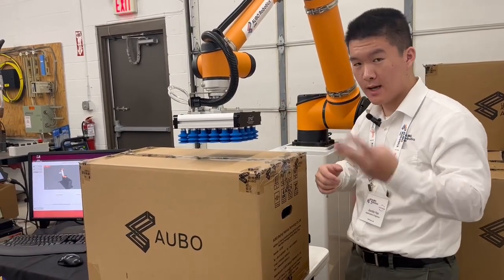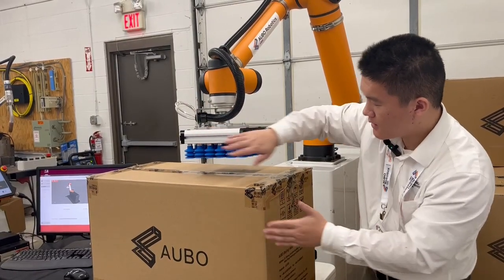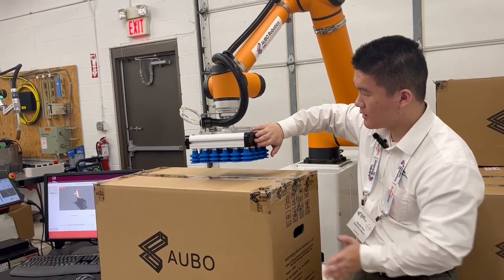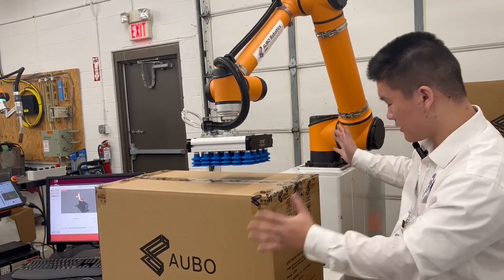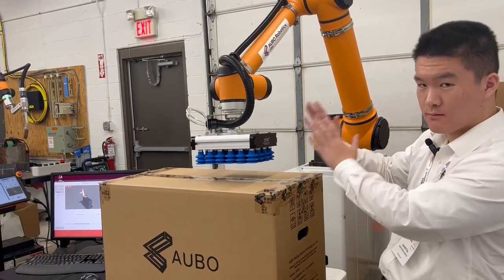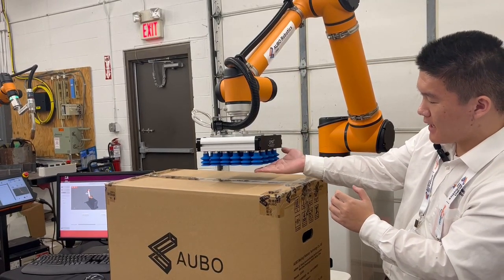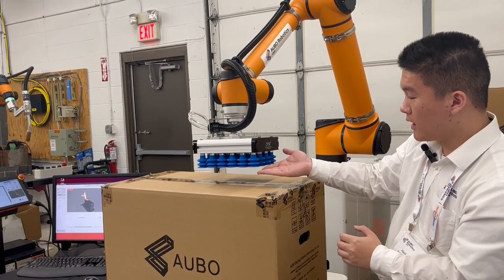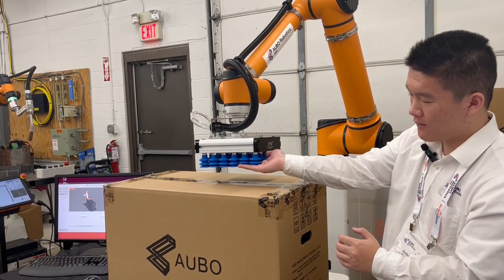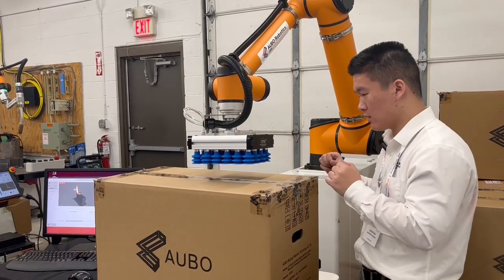So these are the 3 steps we need to do: align this side against this side against this side. Of course, make sure the connector direction that determines the conveyor is correct first. And then we have to lower it such that the suction cup is compressed a little bit, not too much, just enough that you think it's enough to pick up the load that you're working with.